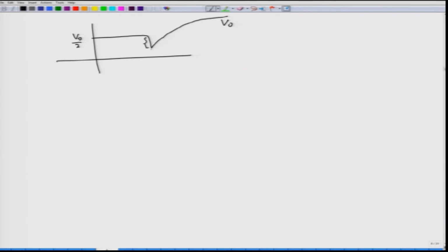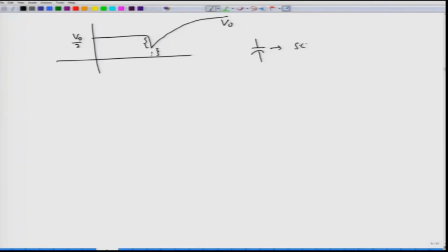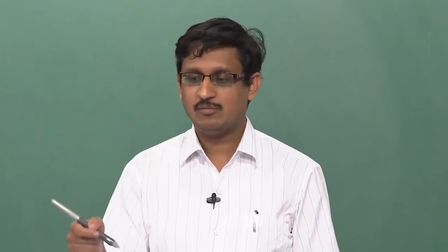So this voltage is not reaching 0. So all this voltage is remaining with us. So what kind of a discontinuity could this be? We know very well that the capacitor must act like a short circuit and hence will be pulling the voltage down, correct. But since the capacitor is not pulling the voltage completely down, there must be some resistive element, okay, which will be less than Z0. Otherwise this voltage would not have been less than like that.